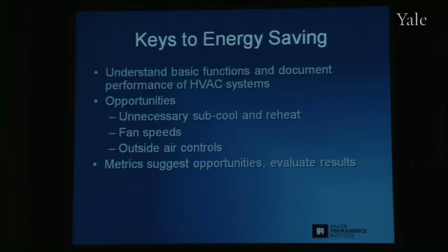The key is you're not going to save money unless you understand how the systems work. Typically, there are low-hanging fruit opportunities. The things that consume energy are cooling the air and heating it back up when you don't have to, in order to dehumidify when you don't have to. Running your fans too much, letting in too much outside air. And use the preservation metrics to really regulate the whole thing.